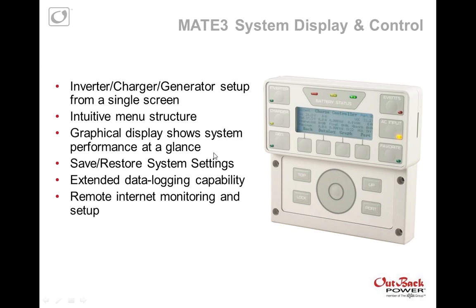One of the things that's kind of nice about this is being able to save and restore system settings. Once you've programmed the system, you can save those settings to an SD card. There's a little SD card that plugs in here. It comes with a 1 gig card, and you can expand up to 4 gigabytes. And you can save those settings away. What's nice is if the customer's system ever goes down, or they need to replace any devices, they can just restore those settings without having to go through and program them. Especially if your customer is remote, it's nice that they're able to do that.